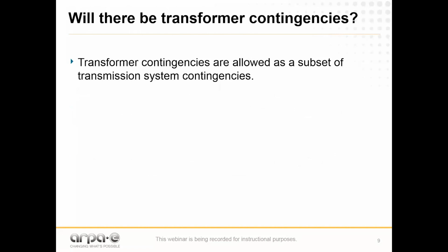Okay? We have a bus branch data set structure to all of our data sets. We do not get into a node breaker model or a bus breaker model. Actually, that type of information will come in challenge 2, not in challenge 1. And so with our bus branch configuration, you either lose a transmission line or you lose a transformer. We are not simulating the operation of a breaker on one side of a transformer or a transmission line and not the other. It is both breakers operate on both ends of the line or transformer. That's the type of contingency that you're going to find. And that happens for the transmission, higher voltage, not subtransmission network.